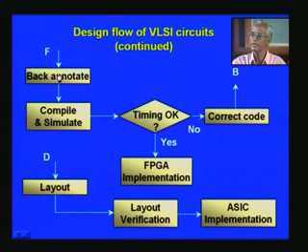So you have to do what is called back annotation. This will update all the gate level delays etc., incorporate all that, and there is a set of commands for this, and running which you get a back annotated file, and this will once again be a .v file. You started with a .v file and out comes a .v file, but the file size will be enormous. If you go through the .v files, it may be very difficult for you to recognize your own design.